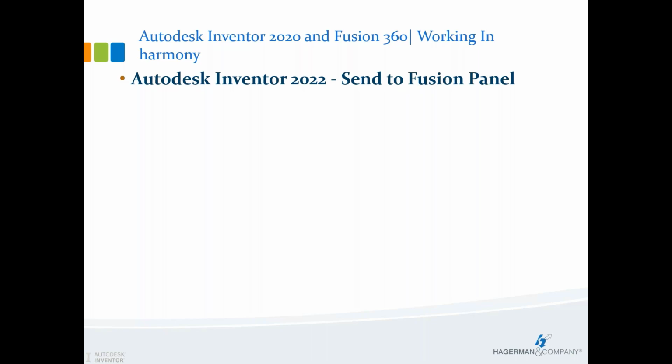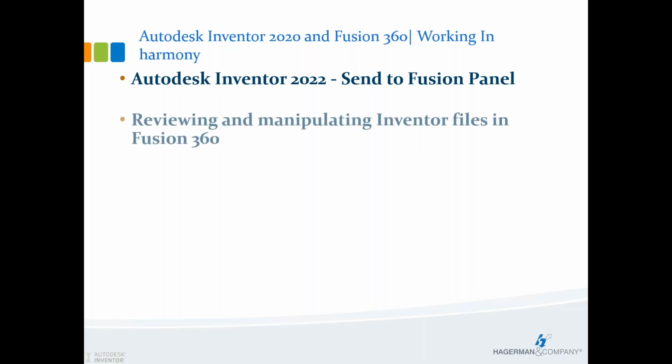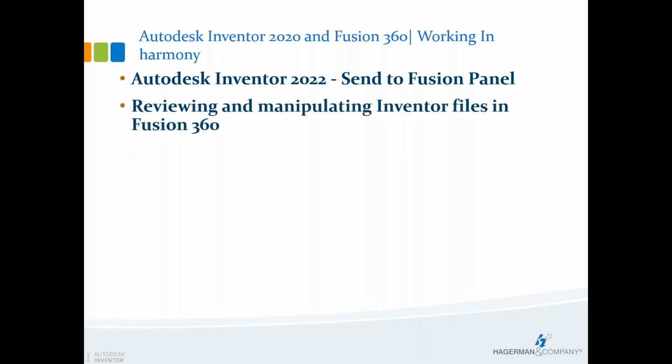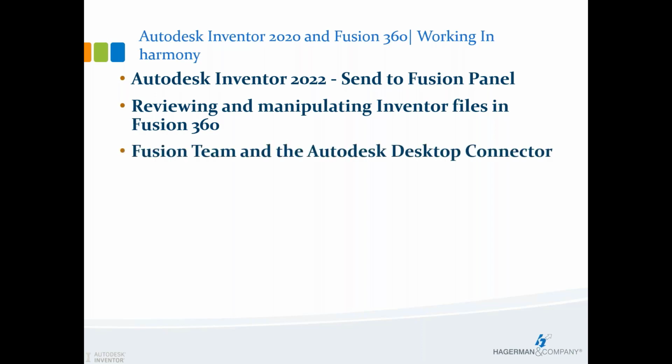This year, Autodesk put in a new panel. It's in the Environments tab. It's the Send to Fusion panel, and we can use this to review our Inventor designs within the Fusion environment, to share those model files within that Fusion environment, and even do some manipulation if we need to.